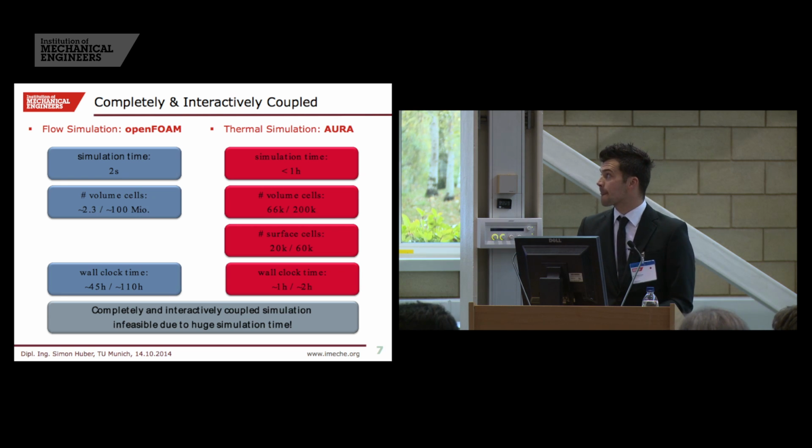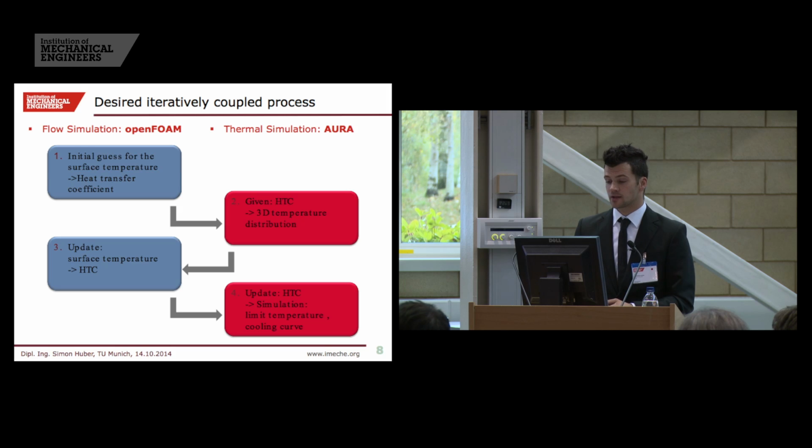So I've come up with a different coupled process. I start with an initial CFD simulation. I have to make a first guess for the surface temperature, and I get an initial guess for the heat transfer coefficient on the surface. Then I start my first thermal simulation.